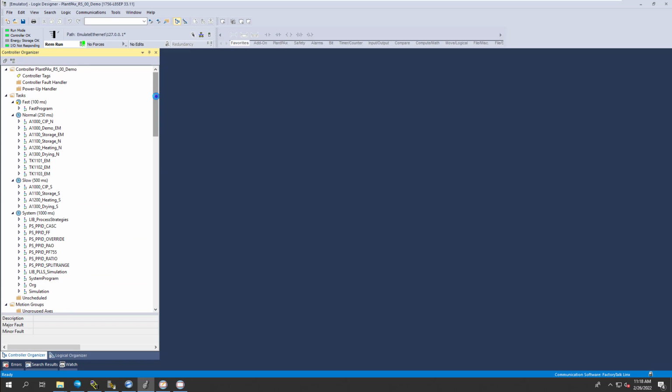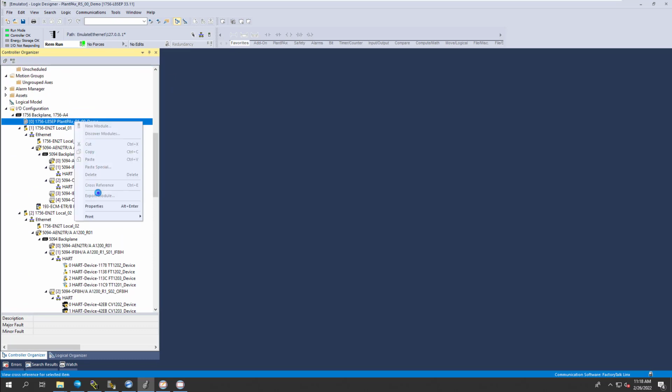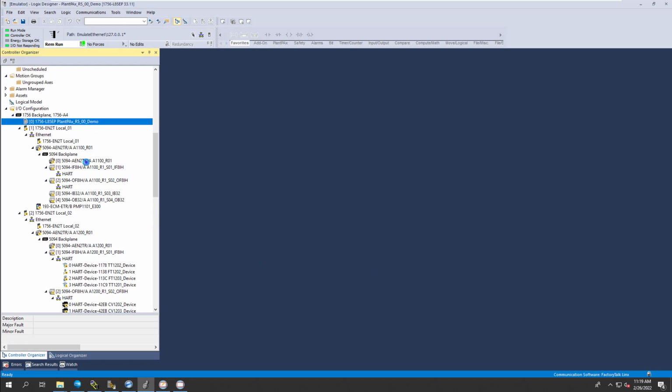which is the PlantPAX 5.0, and that's again using FactoryTalk 12, and that's again going to be using an L8 processor, and that L8 processor is an L8 EP. Again, the E is going to be the Ethernet version. The P stands for made specifically to work for PlantPAX. So in order for you to do that, you would have to have that processor.